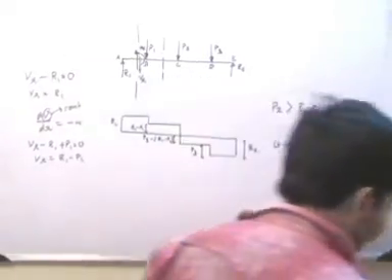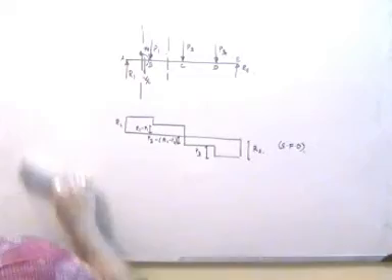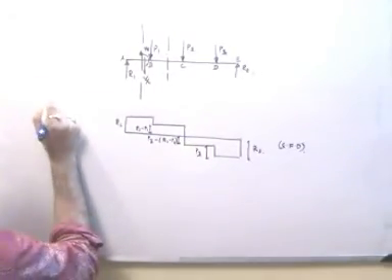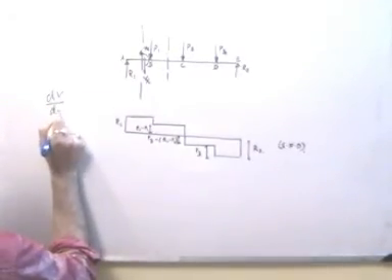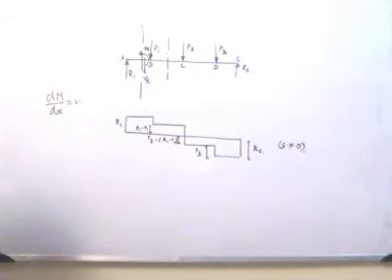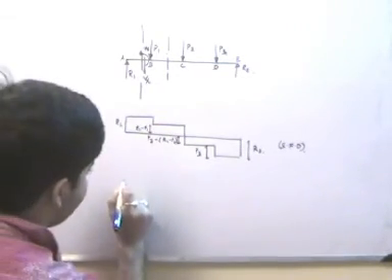These are the two observations that I make from this shear force diagram. The next thing I am going to do is draw the bending moment diagram from this shape. This is my shear force diagram, and I have the relation dM by dx is equal to V, so by this relation I can plot the BMD.